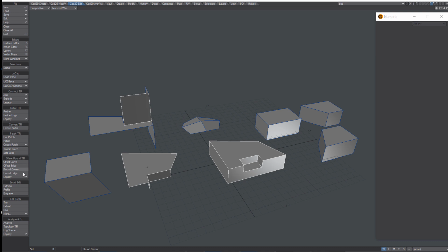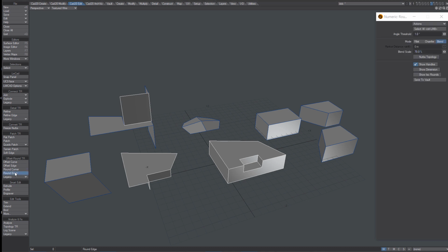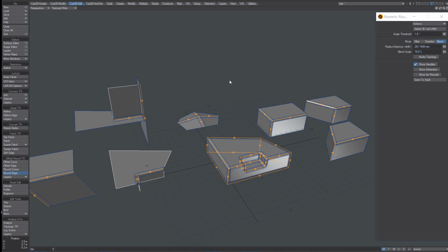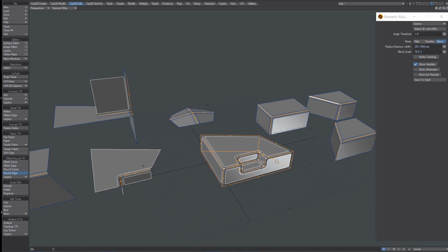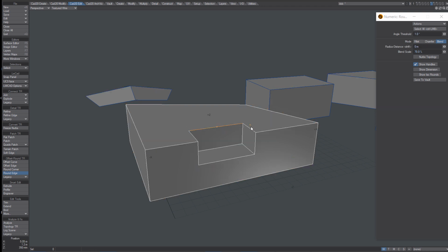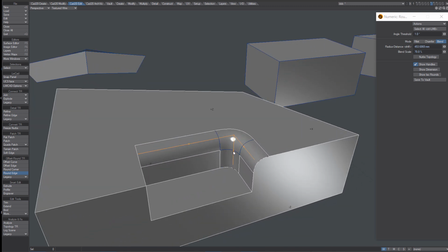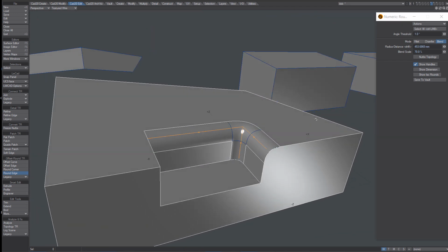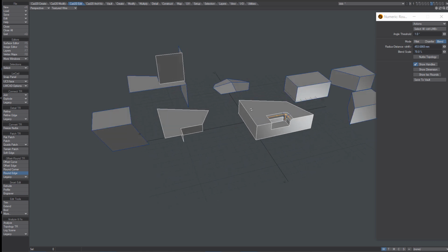The second version of the rounding tool is the round edge tool. This tool is specifically for rounding surface edges. Surfaces can be polygons, flat NURBS surfaces or NURBS surfaces. And we have the same three identical modes: fillet, chamfer, blend. And for a polygonal object, it is absolutely perfect. This tool now works 100% with polygons. All these special cases on these rounded corners are now working very nicely. There are no problems with polygonal objects.